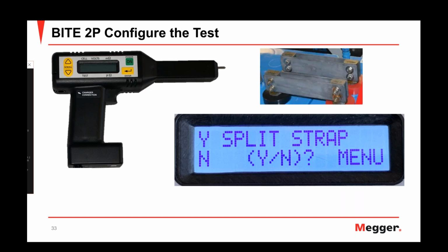So you can see in the picture that we have a split strap situation where you have 2 straps for the same post. The way that this works is, let's say that you have 4 battery straps and you can only get the CT around 2 of those straps. You take the total number of straps and divide it by the number of straps that you can get the CT around. So 4 divided by 2, your multiplier is going to be 2. Go ahead and enter that value into the receiver and push the enter button.